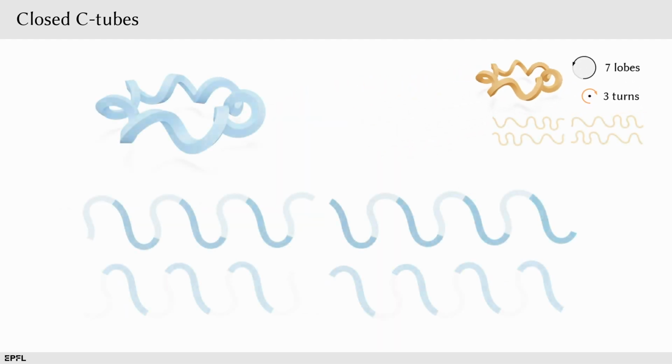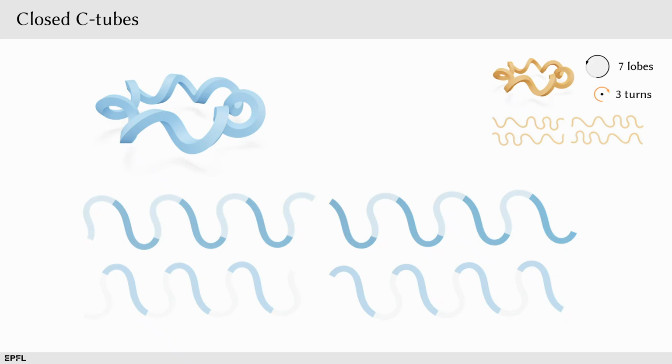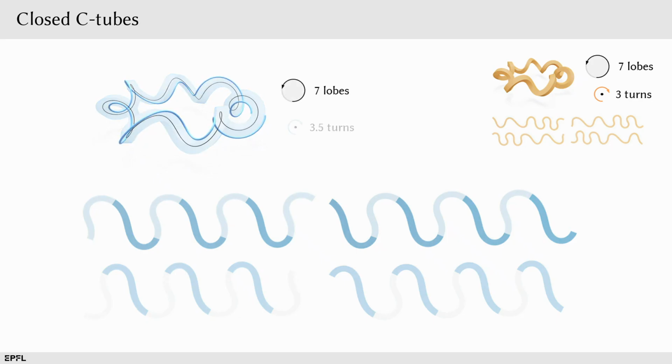Now, when optimizing a cone net instead, what we can control is also the number of turns the ridge curve does around the directrix. So if we set that number to be, for example, 1/2, such that each lobe has exactly half a turn, then the resulting structure becomes self-similar and the strips become modular.